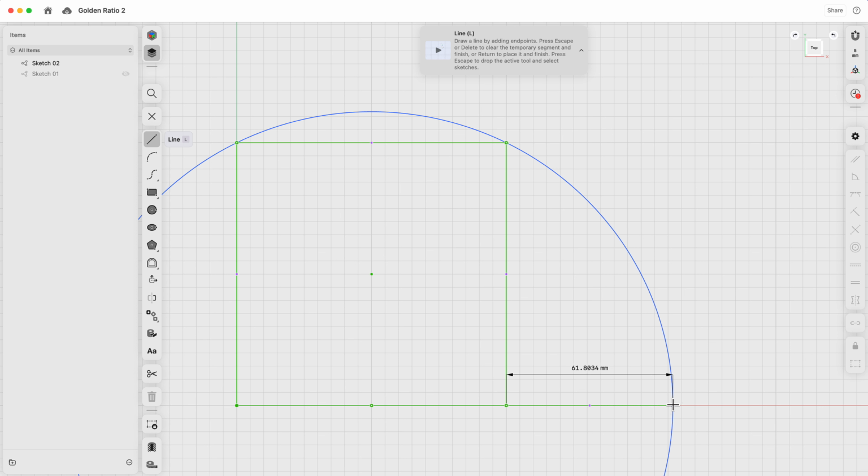Then continue up to make a rectangle. With Shapr3D, you can approach this corner to trigger the apparent intersection. Shapr3D will assume that you want to draw to a point that intersects at 90 degrees to this line. Make sure the vertical line you just drew is exactly 100. Then connect that endpoint to this corner. Then do the same at the bottom.